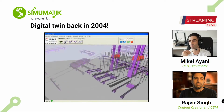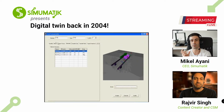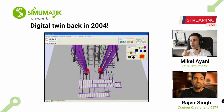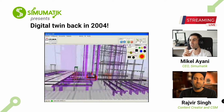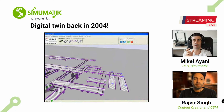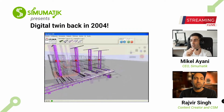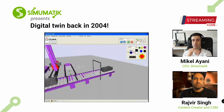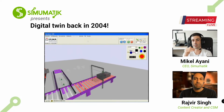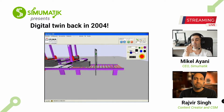But it was cool, and that's why I kind of thought about Omron, because by then I was working mainly with Omron. It was actually the first PLC integration driver I programmed: the Omron FINS protocol to connect to real CPUs. We can mention that this driver is already published and in production in the gateway. Today we will be using the Sysmac Studio simulator driver, but we could have deployed this code to a real CPU, use the FINS protocol and run hardware in the loop.